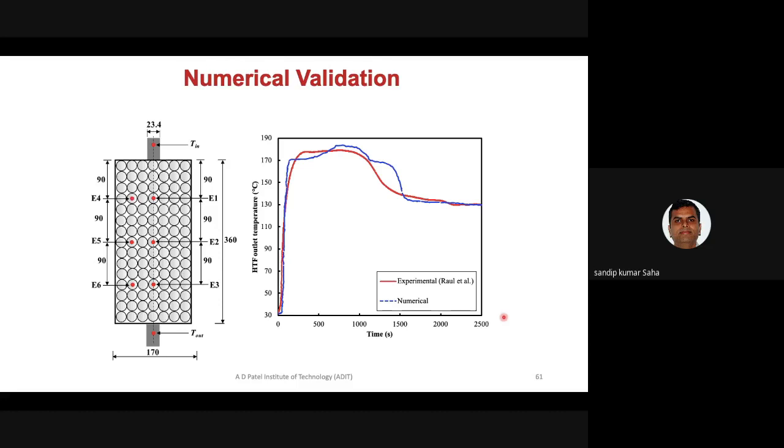It has only one inbuilt Navier-Stokes equation, but it allows you to solve another scalar equation like the energy equation or species equation. So that's why we assume the phase change material will remain solid, although it changes phase from solid to liquid, meaning I am not solving any Navier-Stokes equation, basically.